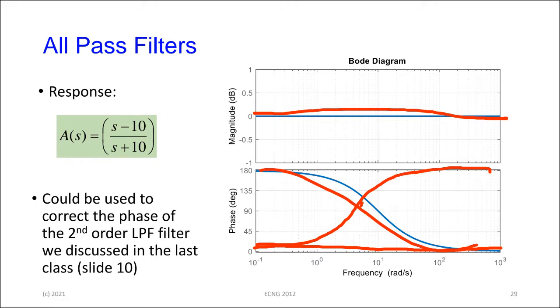So same thing here. We didn't do the design, but just as a comment on it, because this design is a little bit more complex and it's not part of our particular syllabus this time. Having created low pass, high pass, band pass, and band reject filters, all of them have a phase response that leads to some sort of distortion. So there is a corrective measure that can be taken, which is something called a phase shifter or an all-pass filter that does nothing to the amplitude, but attempts to correct the phase distortion that might have been created.